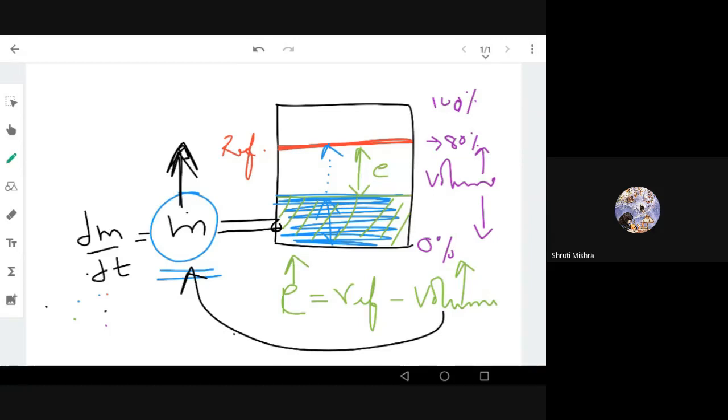This is very important if you are talking about real-time systems. For example, we are talking about a car which is trying to be controlled by reducing the error. What is error here? Maybe the difference between lane 1 and lane 2. If you are going to lane 2, it is dangerous, so reduce the error. This should be very fast. So here the example of a controller is more valid and more important because it is real time.